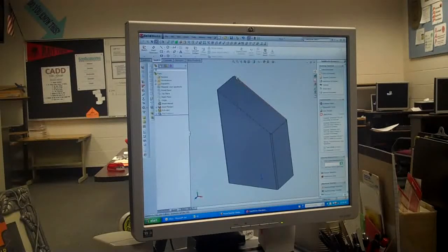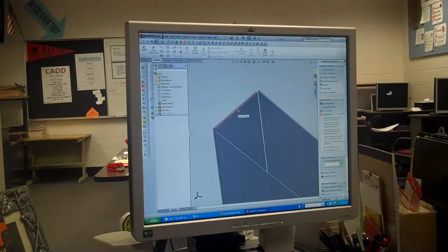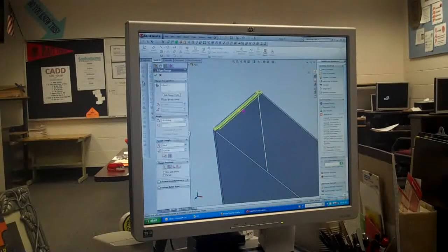The next thing is, because we did a normal cut, we're going to zoom in on this top edge, and we need to create the closure of this top panel. So we're going to use the edge flange tool. Use the third bend outside parameter, and you can actually select the parallel face that it's going to go towards.